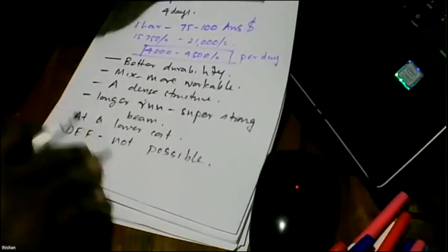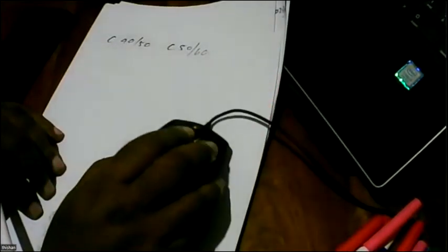Now the moment we look into this matter, you can see we do not have to stop at this level. We went for C35-45 because now we are using only 325 cement. Then you can ask, why not C40-50 or C50-60? So how are we going to achieve this? Let us see what strategies are available for us.